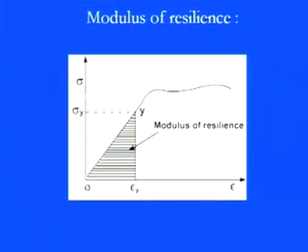So now you see, if you want to draw these things, you can simply limit that particular part. We have a simple tensile test diagram, the stress-strain diagram, and one of the key features is that we always draw the stress and strain in this way. Can you tell me why the stress is always drawn on the y-axis and the strain on the x-axis? The basic reason is the strain is always a measurable and controlled part.